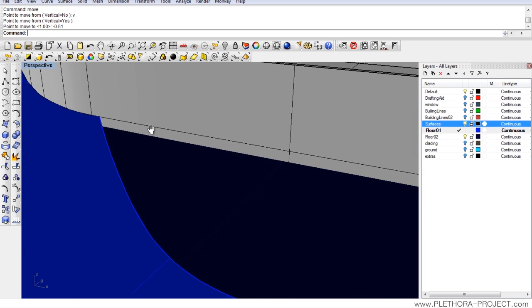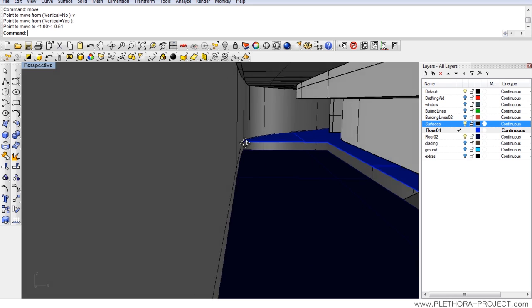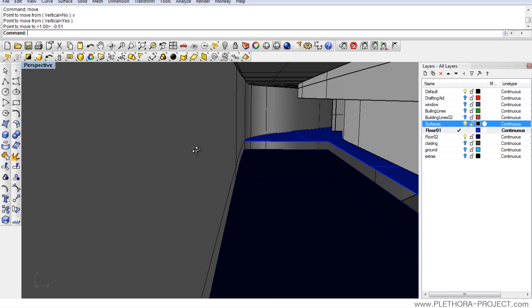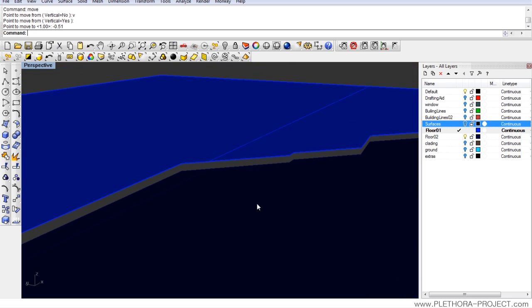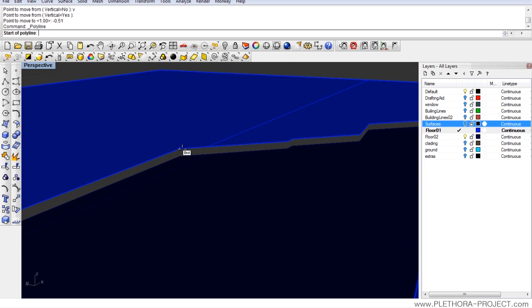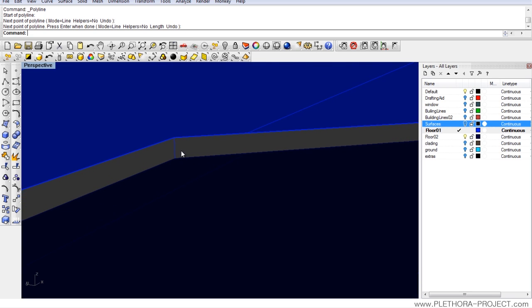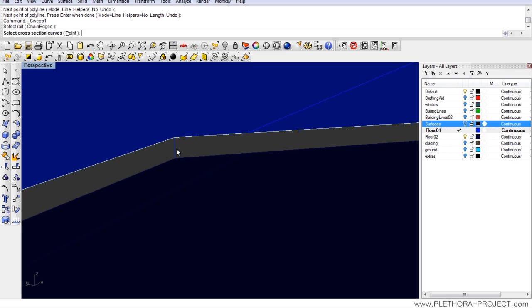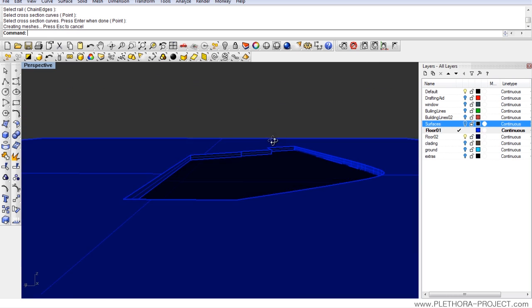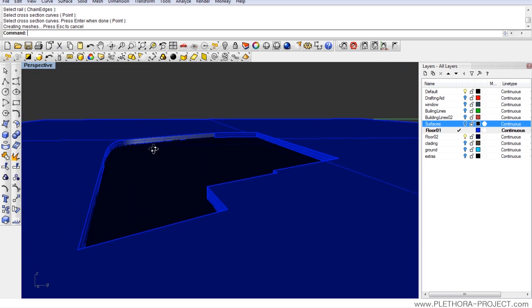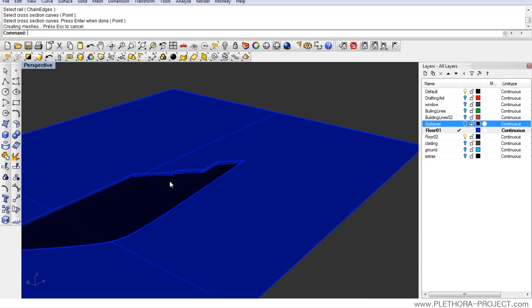And over there we have just at the vertex on the surface, it kind of changed the direction, right? So that's pretty good. So let's go ahead and just draw some of the surfaces. Let's say first let's draw all the boundary, and then let's start doing the ramps and all the other stuff, right? So what I'm gonna do is just do a profile, like a line straight down. And because I do have this curve, the easiest way of actually doing it, I would say, would be sweep. So I'm gonna use this curve as a rail, and then the cross section would be this line. So if we try to do that, we'll see that you'll get all the edge condition all around it in a very quick way. Right? So that's a very good tool.